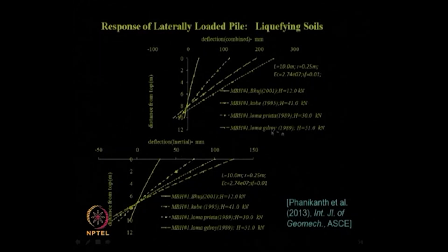This is a type of understanding of what site you are going to address and which problem. Suppose in this site, as a civil engineer you have to propose the remediation technique also. What will be the remediation technique in this case? Suppose some unknown person, unknown in the sense those who are not so conversant with geotechnical earthquake engineering or pile foundations under earthquake condition, what will they propose? They will say improve the soil, go for ground improvement, dynamic improvement, etc., which we have discussed in our previous course on soil dynamics. That is one way possible.